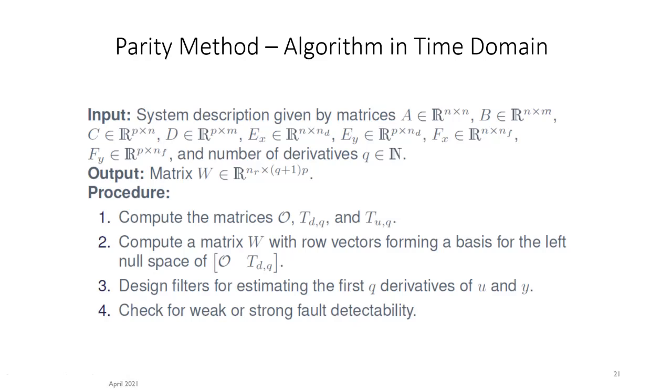Maybe it's somewhat sensitive to noise, or sensitive to high frequency because of the derivation. Exactly. It is actually a big problem, differentiating these signals. Differentiating U is not a problem, because U is something that controls the system. It doesn't have any noise attached to that. But differentiating the output is a problem, because output is always added with noise.